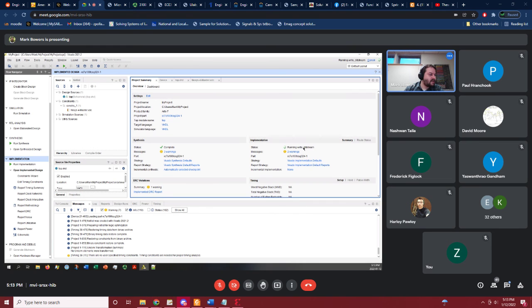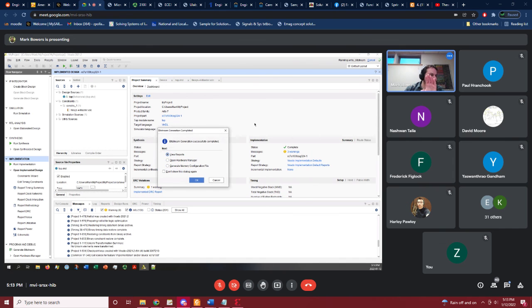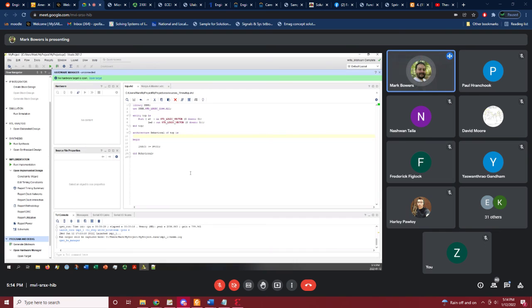So it actually should be programming it on the board. It's taking a second here. Again, it's a pretty beefy program. There's a button to test your code debug. Okay, so it made the bitstream now, and what we can do here is select Open Hardware Manager, and here we go, it says no hardware target is open. We're going to go Open Target, Auto Connect, and if everything's connected just right, it should go and run it on the board.